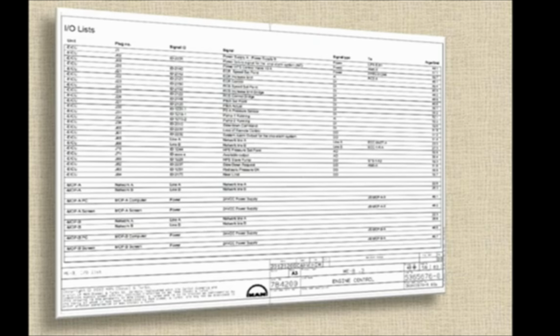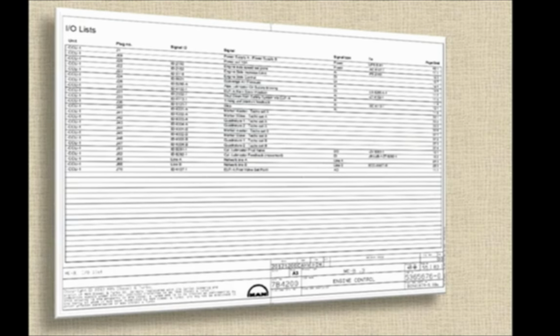And this is the circuit diagram for that. In the EICU, what channels are connected, and which plug is connected to which channel, which system or sensors, is given in the chart like that. CCU1 is also given as a sample, and with that you can find out which channel is going to which sensor or valve or wherever it is going. You can easily trace it out from here.